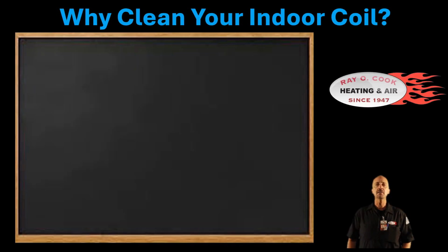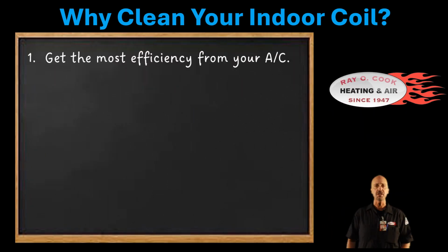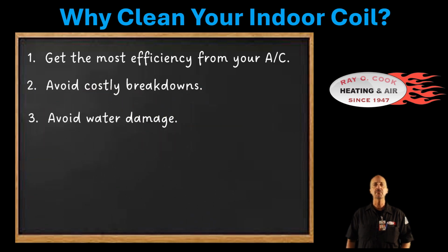So why clean your indoor coil? Number one, you can get the most efficiency out of your cooling system with a clean indoor coil. Number two, costly breakdowns can be avoided when your system is running at its peak performance. Number three, you can avoid a major problem by preventing ceiling or floor damage should a dirty coil cause condensate water to back up and overflow into your home.